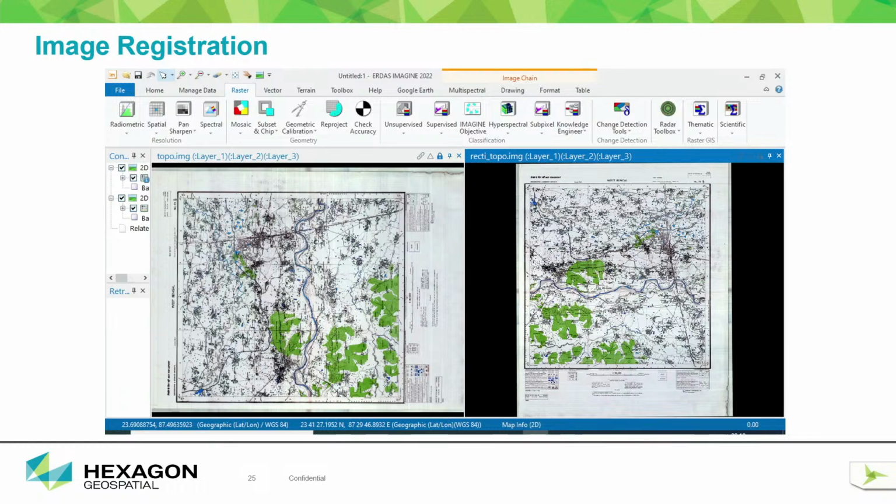Now you can see that when we click on this map, you could not find this type of information before. After geometric correction, we gave some GCP points and told it to use these GCP points to process the image for geometric correction, in the geographic projection and WGS 84 datum. And now you can see that the latitude and longitude values are coming. Are you getting my points?